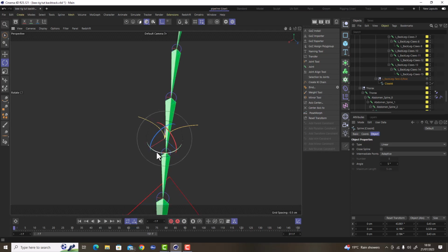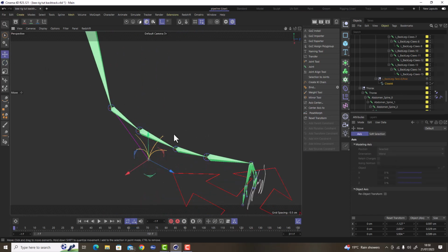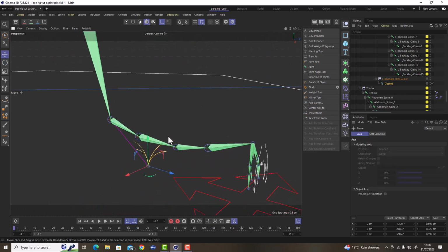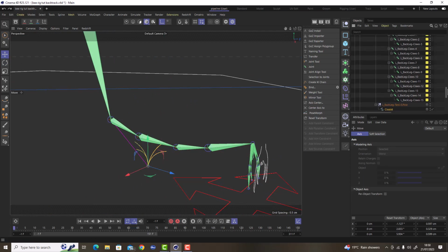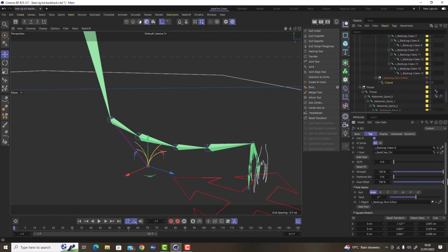So we will hold that shift key, 45 degrees in our particular case. There we go. And of course we've got that movement there. Well, we will have that movement there. I'm going to go back into my IK settings, and I'm just going to drag and drop this new controller in place. You shouldn't see anything pop or move. If you do, then something's done wrong.